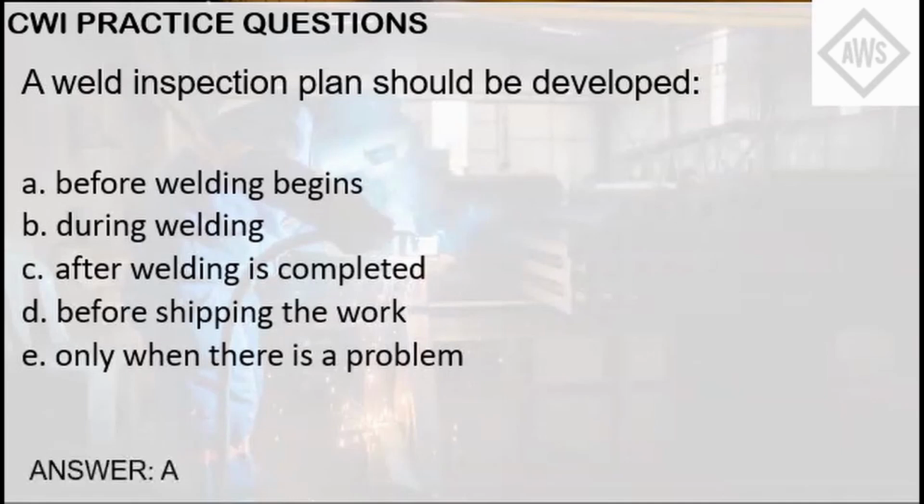Similar to an inspection test plan, which must be approved prior to the actual inspection activity, this inspection plan also defines the hold points in which the welding inspector will inspect the result of an activity. For example, the root pass will not be able to proceed to the next activity if and only if it yielded a positive result. These hold points will be difficult to implement if these inspection plans are done anytime after the welding activity begins.